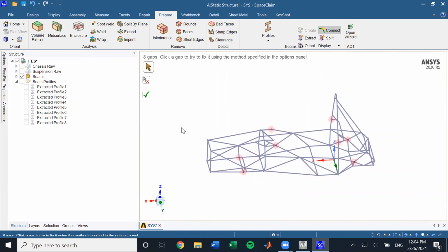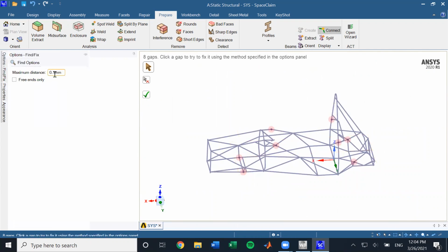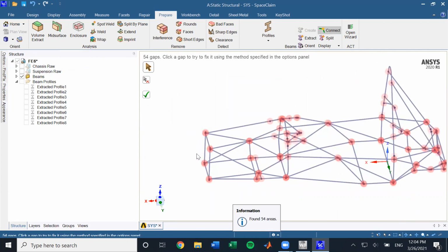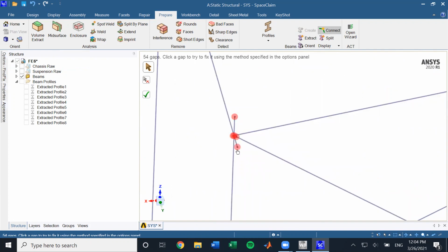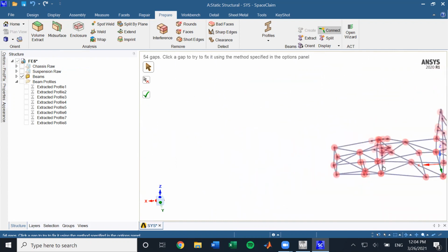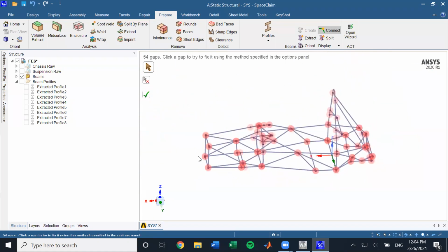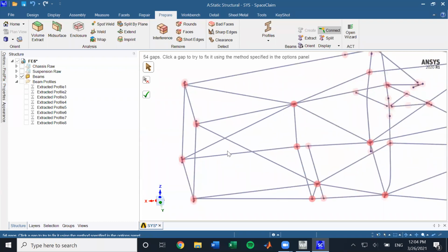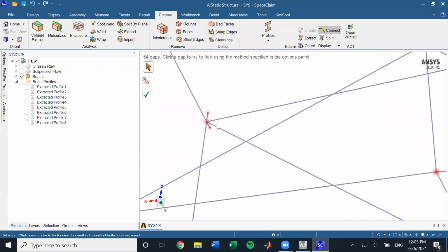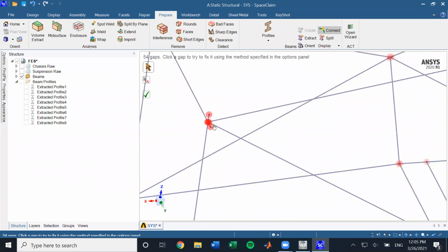And if you go into the left here for options, let's make the max distance really large. Let's just make it 50 millimeters. So it's saying anything within 50 millimeters that isn't really connected is just going to be highlighted in red as something that needs to be fixed. The reason we start big and then go small will become apparent as we do it, but it's mostly just to fix the big things first and then go more into the details afterwards.